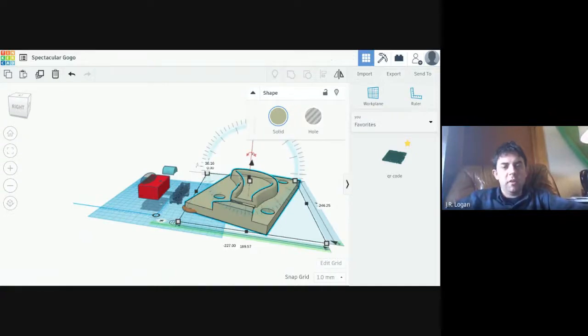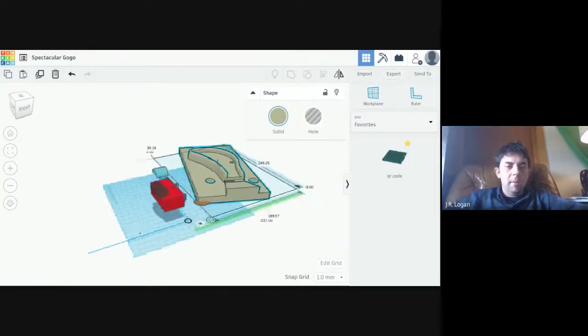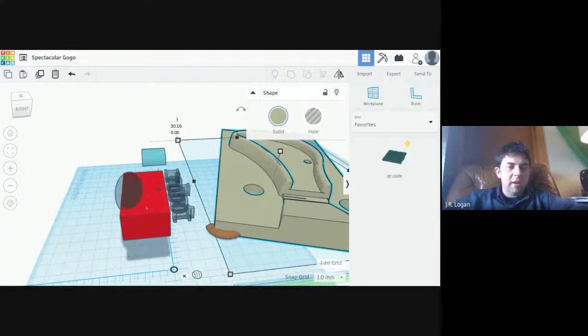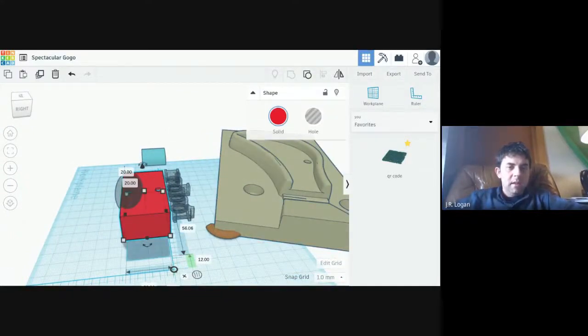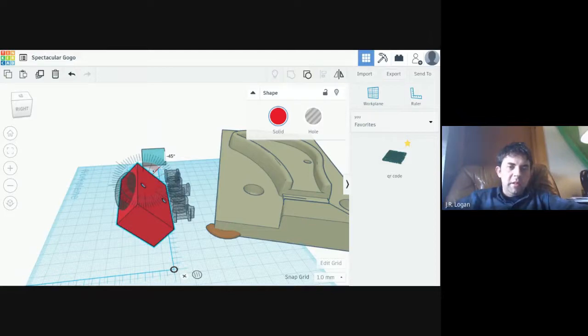It's jumping to those, and that makes it easier to make sure that you're exactly aligning it to the bottom plane. This took me a little while to figure out. If you move your mouse to the outside of that circle, it now is a free rotation. If you don't realize that and you're trying to do the rotation, you're like, why is it jumping and sometimes it's smooth? Well, it's based on where in the circle you are. So this allows you any degree, and this gives you only the predefined degrees that are on that circle.